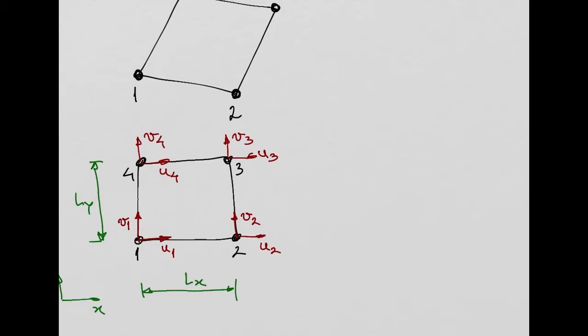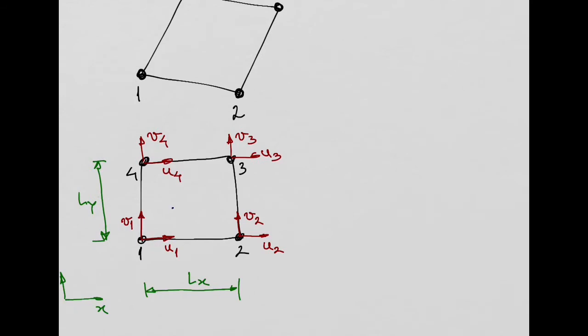And for example, imagine you want to get, so I'm going to represent in blue, the coordinate of this point here in the element. So let's say you want to get the x and y of this point. What you do is, for the x, you do the summation of the shape functions of the element times the nodal coordinates of the point.